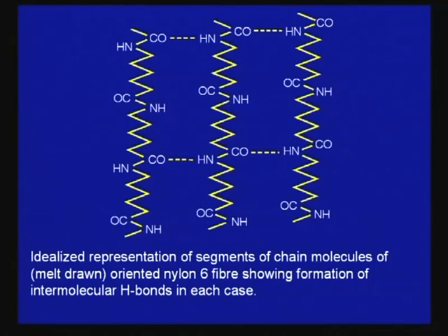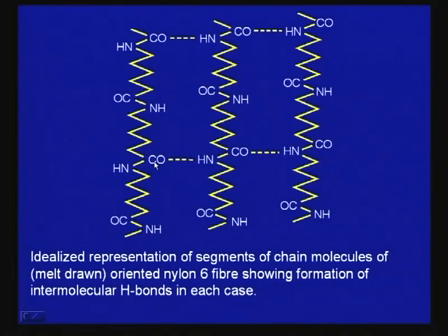Here is another example of a polymer, say polyamide, nylons or polypeptides. In polyamides, the helical structure in polypeptides, in proteins, the structure is solely dependent on this hydrogen bonding as well as cross linking. Their cross linking atom might be sulfur and other atoms in proteins. In polyamides, the strength is dependent on the high polar interaction arising out of this interaction between oxygen and nitrogen present in separate molecules. So, these also form strong hydrogen bonds. These hydrogen bonds actually control its solubility in a solvent, control its melting temperature.